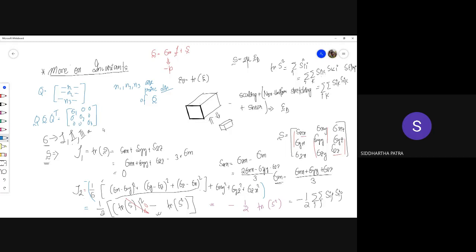Now, as you might know, the stress tensor has, okay, we just wrote this down, two parts, one where it is hydrostatic. So when it comes to the stress tensor, we say hydrostatic. When it comes to the strain tensor, we say volumetric. So one part is hydrostatic, the other part is deviatoric.